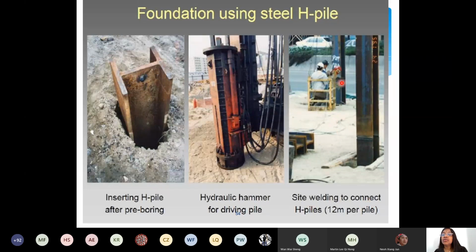Side welding. So one pile is driven, another pile is coming in. They are welding it to connect it. They are connected by welding. So piles are placed one on another, right? That's why it's called pile foundation. The pipes or the sections are put one on another into the ground with the proper joints. Joints are very important. Care should be taken to firm it. Allow some time. If it is concrete, allow some time for curing.